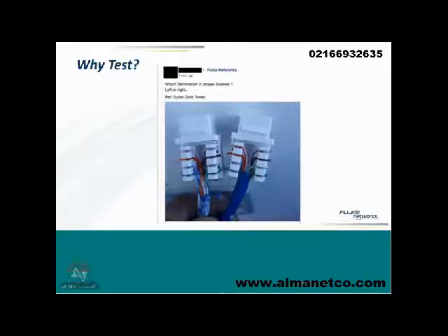I showed this to a number of experts in our company who are on the TIA and IEEE committees. They should know good cabling when they see it. Their answer was, yeah, they both look pretty good, but I probably want to test them to make sure they're good. You can't just tell by looking at a cable whether or not it's good. The one on the left shows a little bit better workmanship, but they both might work fine. I don't know if that's Cat 5 or Cat 6A, but with a cable tester, I could figure all that out and know whether or not it's going to work. The other option, of course, is to just plug it in and pray that it works. Plug and pray, as they like to call it. So that's why we want to test.